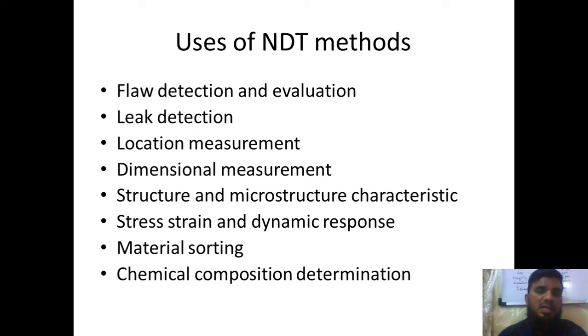So in such cases, what we can do is use some kind of non-destructive testing methods from the outside of the source itself. For example, from outside the earth itself. If your whole petrol pipeline is going beneath the ocean, from outside the ocean itself you can send some high frequency rays which pass through the water and even through the pipe. Based upon the reflection of the acoustic waves, or by using the ultrasonic beam, and the way it is reflected back, you can identify the leakages in the pipeline.